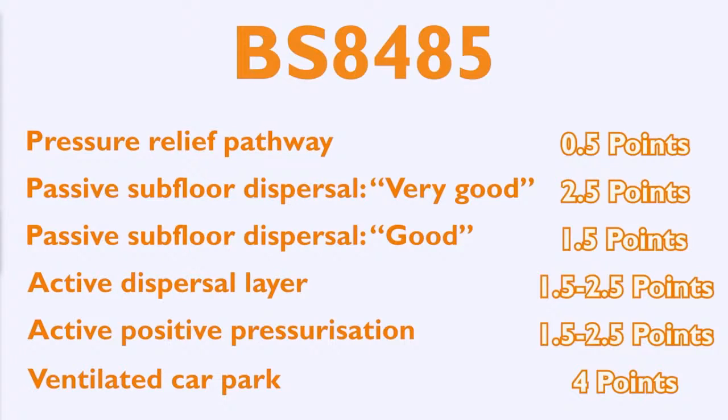active systems. Active systems use powered fans to remove gas, which in theory makes the systems more consistent and potentially more effective at removing gas. But problems can occur if fans are switched off for any reason, such as during change of tenancy or sale. For this reason, the points associated with active systems were reduced by the 2018 amendments so that in most cases additional passive protection would be required.